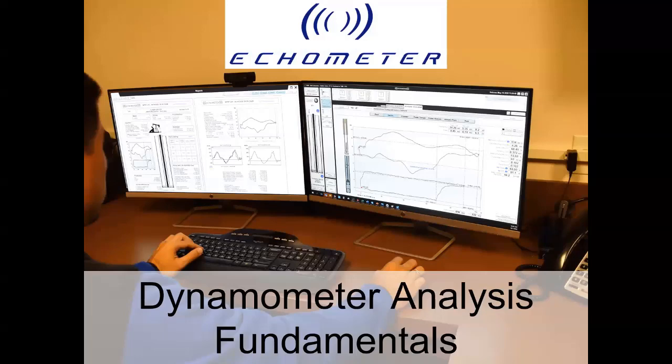Gearbox torque is another portion of the report that you can review if you input the necessary information in the software, like pumping unit, counterweights, crank information. The software will normally have enough information to understand gearbox balance and loading, but also if you have an electrical motor and a power probe, you could simultaneously record power data. We don't have enough time to talk about power, but it can be a simultaneous acquisition when you're acquiring dynamometer data.